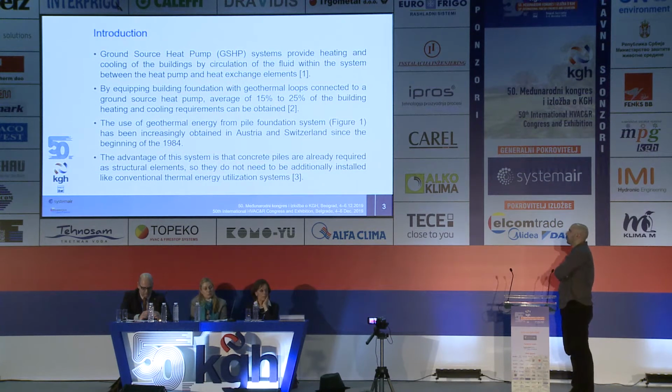Ground source heat pumps, or GSHP systems, provide heating and cooling of the buildings by circulation of the fluid within the system between the heat pump and heat exchange elements. When we equip building foundations with geothermal loops connected to a GSHP system, we can obtain an average of about 15 to 25% of the building heating and cooling requirements.